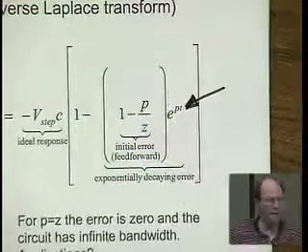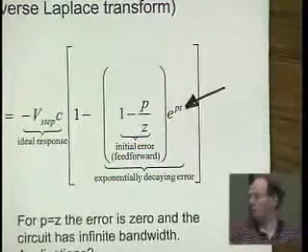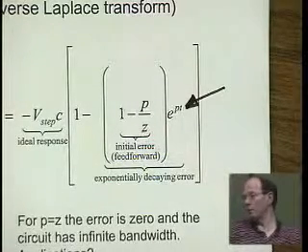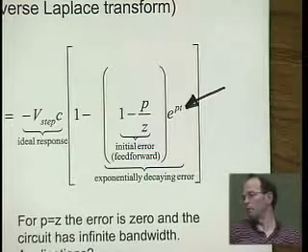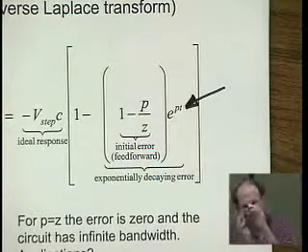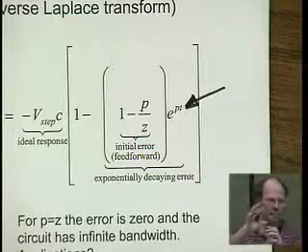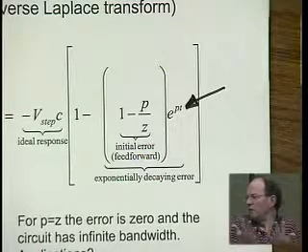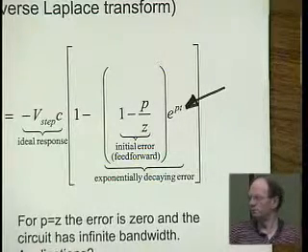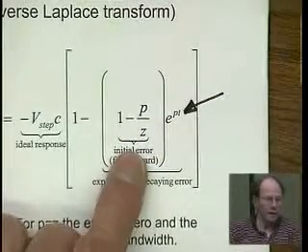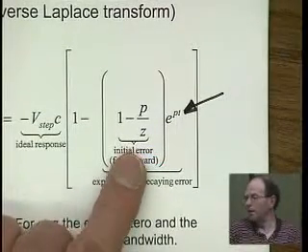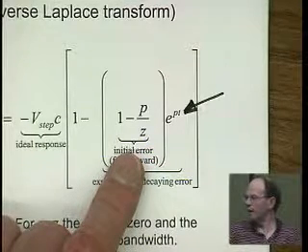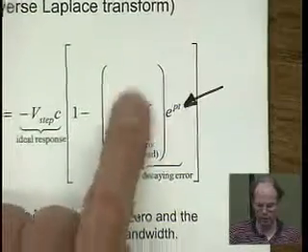One of them is, how precisely can you match P and C? Percent, right? Well, if you look at it on the screen of your oscilloscope, probably the matching is not 1%, it's probably something like 5%, because the screen is small, your eyes are limited, and the beam is wide. So it's not very accurate. But you don't need it more accurate than a few percent, which is fine. So accuracy is the number one reason. On the other hand, in an A to D converter, you want this error to be 10 to the -5 or something like that, and then really you never can get this matched.